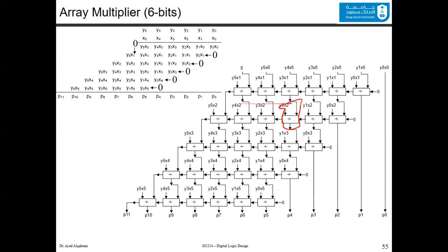There are special cases around. For example, at the end here, the carry output of the last digit is actually one of the inputs of the next adder. So one of the inputs is here, and you keep doing this for the last adders. Also, at the beginning of each row of these adders, you have a carry input of 0.